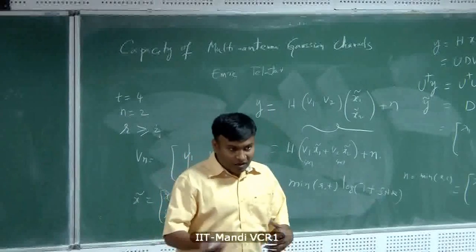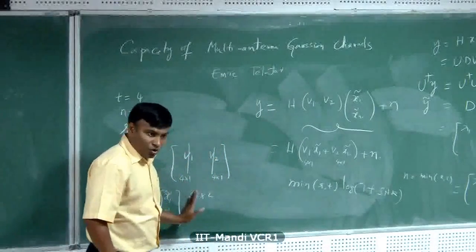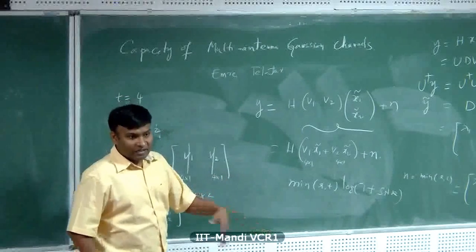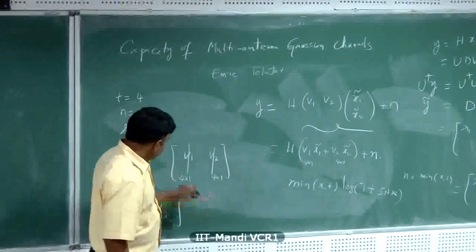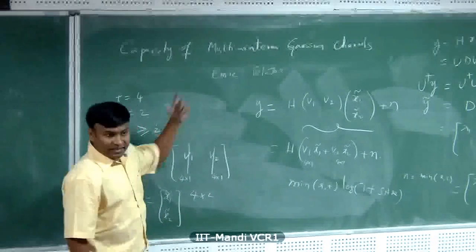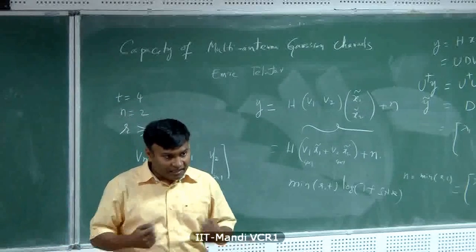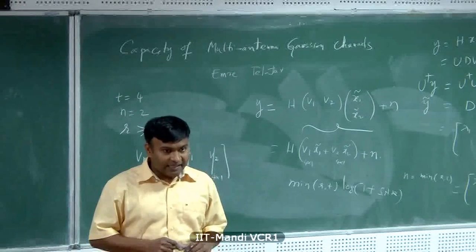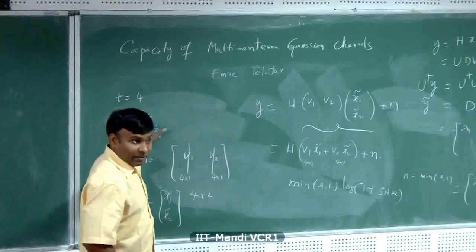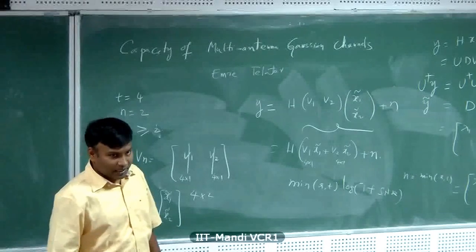So, to cut the long story short, these transmit antennas do play a role to increase the beamforming advantage, or so-called array gain, when you limit the number of streams to 2 and have a higher number of antennas. But that benefit is quite marginal. The real rate increase is given by the number of streams. Okay?